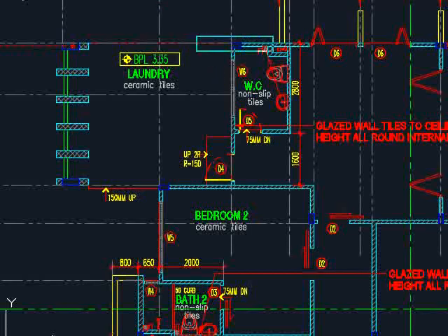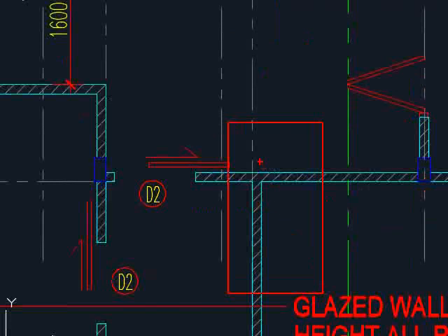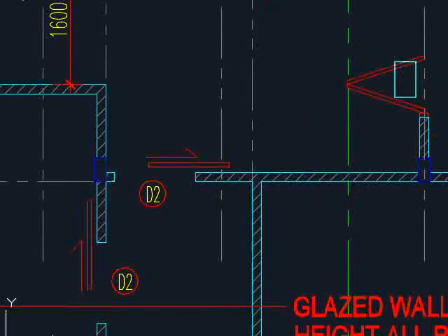You will need to observe the grid line as compared to the members of the structures for you to know the exact locations of that particular member, and observe the alignment of the member, whether the grid line is on the side of the wall, something like this, or whether it is arranged in the center line of the members, something like this, the grid line is at the center of the wall.